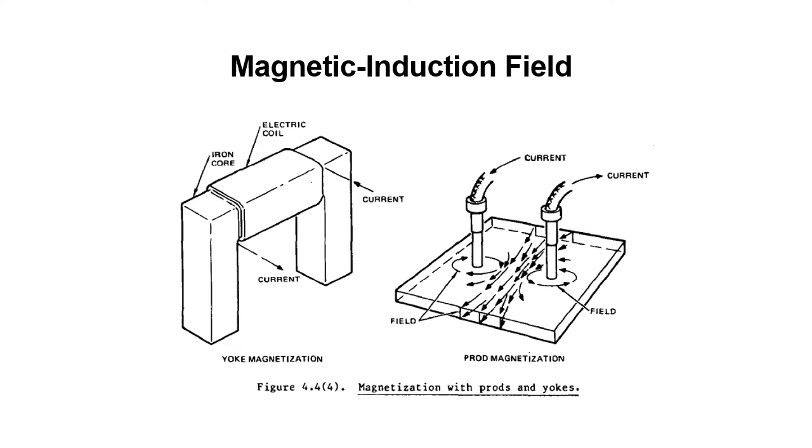However, if the part under inspection is magnetized by injecting current into its surface, care must be taken to avoid arcing, as this may severely damage the surface, particularly whenever handheld prods are used to inject current. Arcing tends to occur whenever the current contacts are dirty or are moved during excitation. A simple way around the arcing problem is to securely clamp the contacts to a clean area. When magnetization is induced by placing the part in an external magnetic field, the arcing problem does not occur.